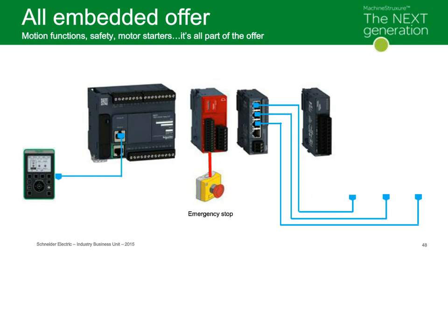And the TM3 I/O modules, we have more of them than ever before, but what we also did is we integrated safety into an I/O module. So before, you had to take a safety relay and attach the I/O points from that back to your controller for communication capabilities. Well, now, instead of doing that, you're able to communicate directly over the I/O backplane from the PLC to the safety module and be able to get status and all that information right back on your PLC.